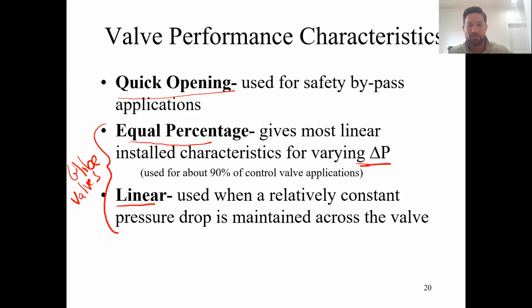Right, so there are pump characteristics that determine the delta P; the pressure drop is a function of flow rate. In some cases, pressure drop is not a function of flow rate, for example, hydrostatic head. If you have a gravity-driven system, the pressure generated is always going to be constant, and therefore we don't experience large changes in pressure drop.